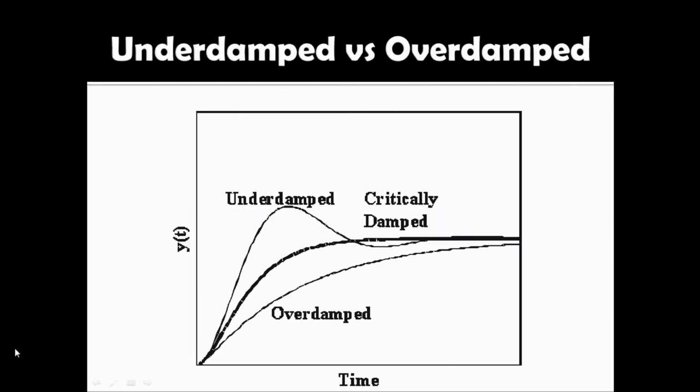Underdamped versus overdamped. The response can be classified as one of three types of damping that describe the output in relation to the steady state response. An underdamped response is one that oscillates within a decaying envelope. The overdamped response is a decay of transient current without oscillations. The critically damped response represents the circuit response that decays in the fastest possible time without going into oscillations.